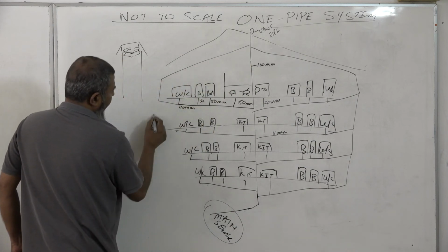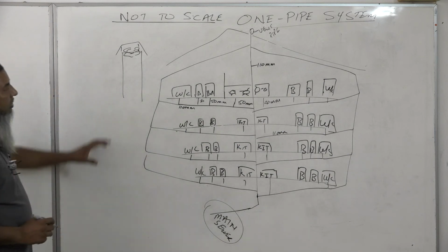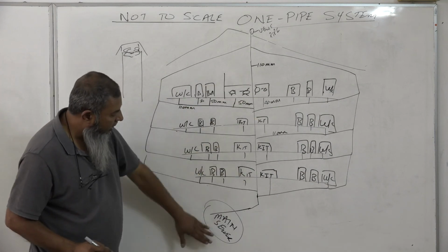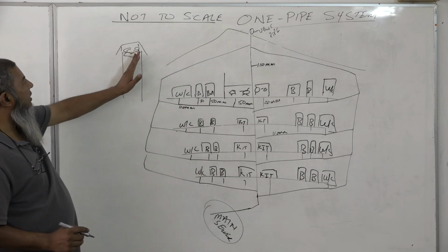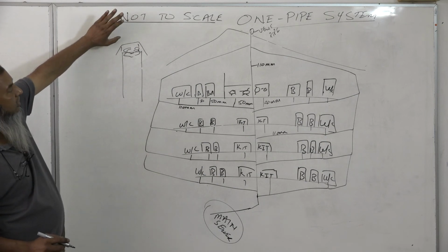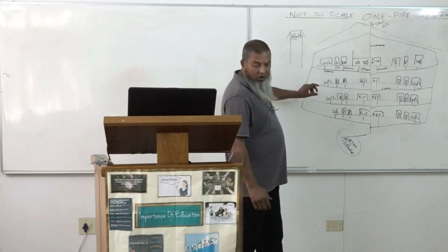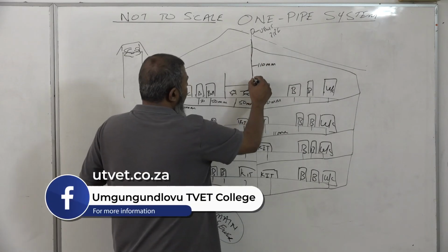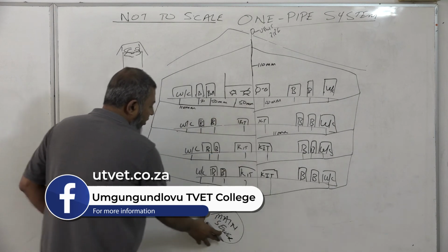Venting, venting, venting. So this is what we call a one pipe system, where everything leads to one common drain going out to your main council supply. Everything is vented to one pipe. Your vent pipe is there. It is suitable and stable. To recap very quickly, people, the one pipe system. All our pipes lead into one common sewer. Everything, all our appliances get connected to one pipe leading to one drain.